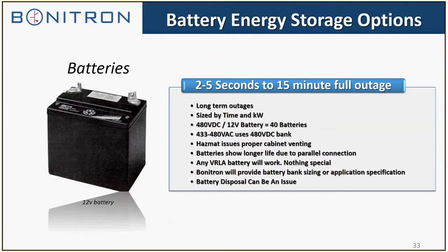One advantage to our type of configuration is that with a UPS, you have a series solution, so it's constantly providing the AC to the front end of the drive. That means the UPS is constantly active in one way or another, and that will cause wear and tear on the batteries over a period of time. With us being a parallel solution, we're off until the DC bus tells us to turn on, then we pull from the batteries. Usually battery vendors will tell you 5-year battery string change outs.